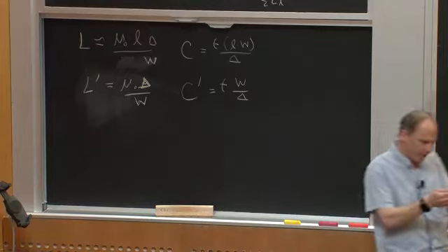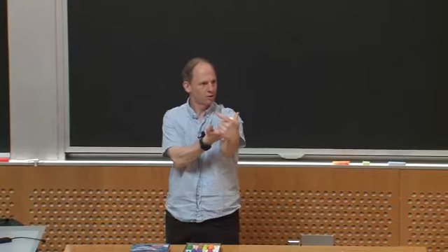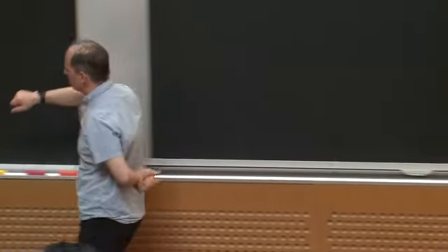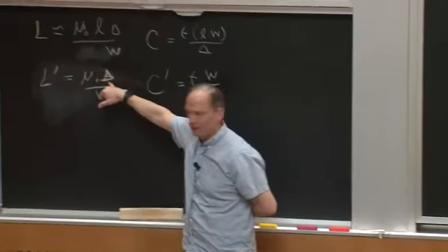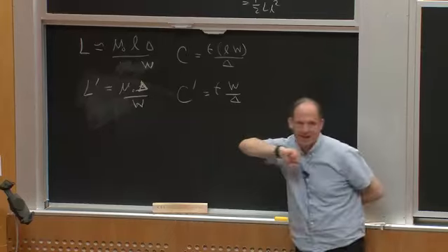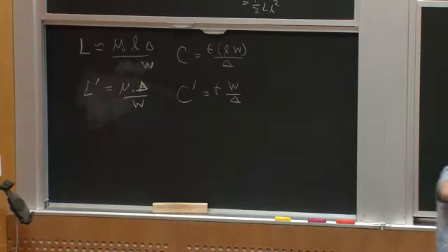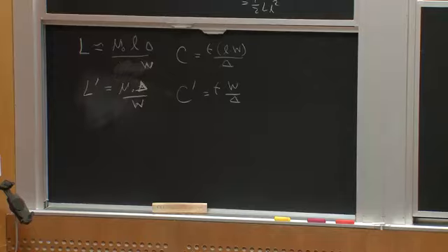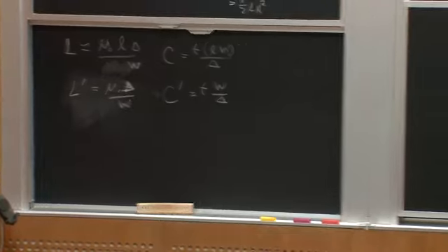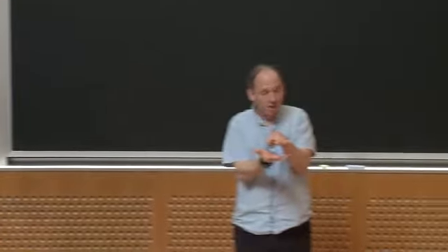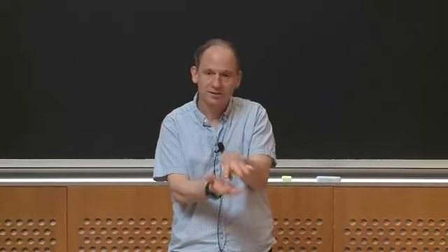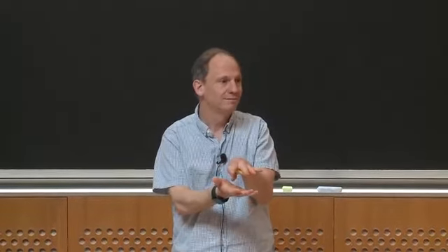Okay? So if I'm thinking about some trace and its return, or two pieces of metal close to each other, whatever I do to reduce the inductance increases the capacitance and vice versa. So in some cases, if I do the best thing I can do, I'm trading capacitance for inductance, and I've got to decide which I dislike less.